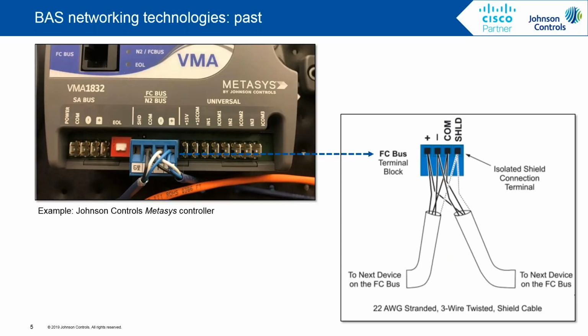But as the building automation system industry has evolved over time, the deficiencies of serial-based field bus networks have become more problematic. And for those installers out there, they probably know this, but one of the biggest headaches with serial or RS-485 based field bus networks is troubleshooting their issues: setting them up initially, getting them to work properly at initial startup, but then any type of issues that might pop up ongoing.